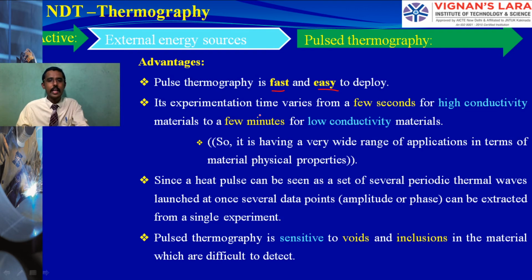Its experiment time varies from a few seconds for high conductivity materials to a few minutes for low conductivity materials. So it depends. With a high conductive material, the heat source is easily absorbed, easily goes in, reaches the defect, reaches the discontinuity and comes back. We are understanding the distribution of heat. If it is low conducting, the heat travels slowly, spreads out and reaches the defect, and that we are going to capture in multiple forms of